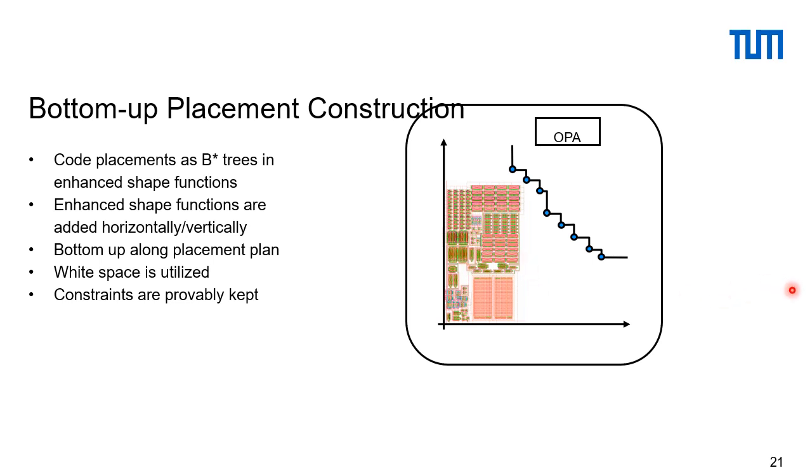You can add that manually and just restart the whole process with an additional constraint. So this is a very nice example how, getting the constraint, getting the knowledge about symmetry with design knowledge, looking at the netlist, setting it up automatically, we can create a placement process out of that.